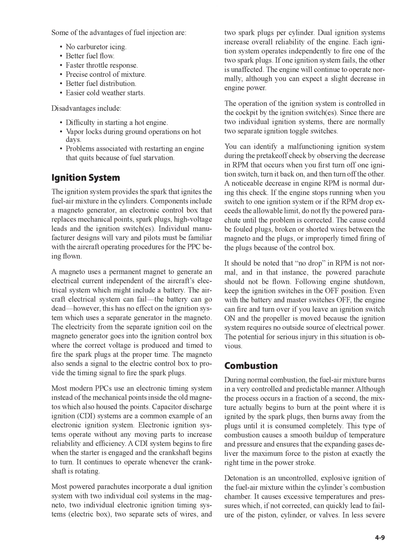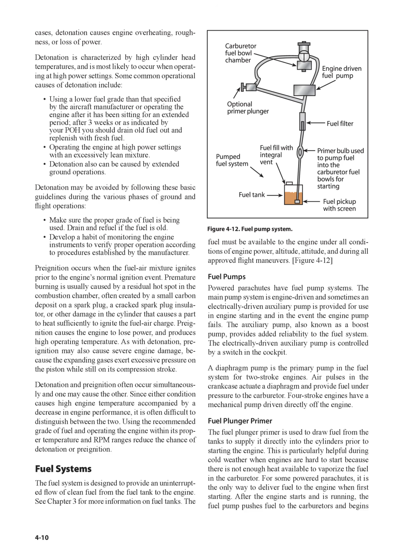Detonation is an uncontrolled, explosive ignition of the fuel-air mixture within the cylinder's combustion chamber. It causes excessive temperatures and pressures which, if not corrected, can quickly lead to failure of the piston, cylinder, or valves. In less severe cases, detonation causes engine overheating, roughness, or loss of power.